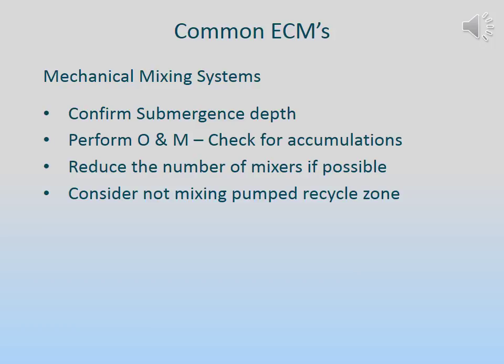Looking at the mechanical mixers, we want to make sure that the submergence depth is what is recommended. Perform the operation and maintenance checks and include checking for accumulations on the mixer. Anything running around in circles with that mixer is probably causing extra energy consumption by creating drag. Reduce the number of mixers if possible. Consider not mixing in the pumped recycled zone. Again, that is another case where we look at the nitrate recycle zone, and since we have pumped recycle going to this zone, maybe it is not necessary to also run a mixer in this zone.